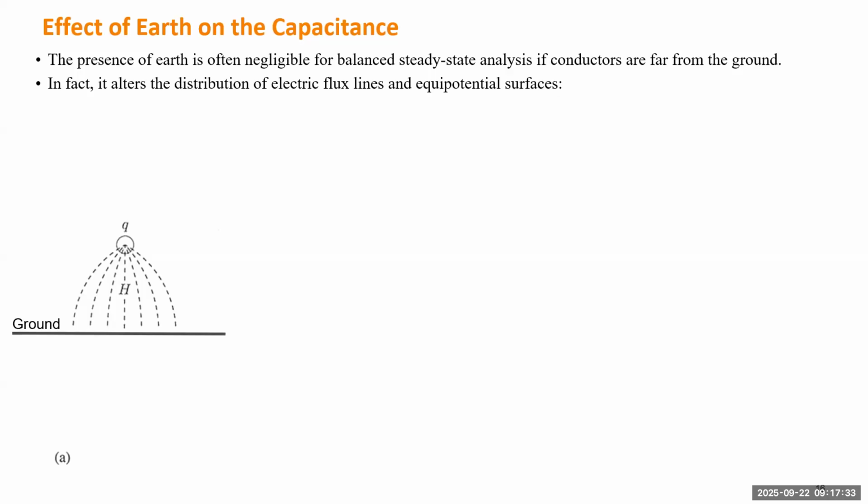We first assume each conductor carries a certain charge Q, and that will make an electric field. Based on the density of the electric flux, we calculate the potential, or the work you need to do to carry a unit charge from one point to another point. So usually we want to calculate the charge moving from the conductor to a certain distance. That could be another conductor.